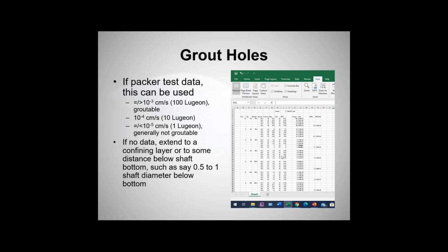Over here on the right, this is not designed for you to read, but that's simply the raw data for hydraulic conductivity testing given in the geotechnical data report. And the raw data is really important so that the grouting contractor can make their own interpretation of that information, because they may have an empirical way of looking at that data that they need the raw data for. So you've got raw data over here. Here's the raw data summarized. And then here's a calculation of hydraulic conductivities for multiple step tests, and then an average Lugeon value. And again, understanding Lugeon values is important; it's gone over in the previous webinars.